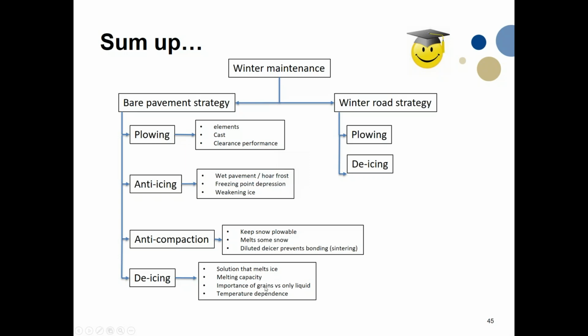But it is important to have a grain, which can be viewed as a storage of chemical that can go and keep up your concentration. Any chemical has a certain melting capacity, and the melting capacity of a solid de-icer is much higher than a liquid de-icer. The last part of it was a high temperature dependence. So it is easier to succeed with your de-icing operations if you're close to the melting point rather than if you're very far away from the melting point.